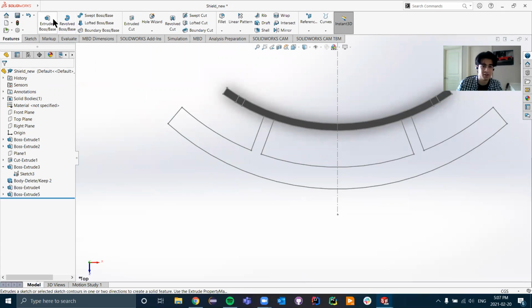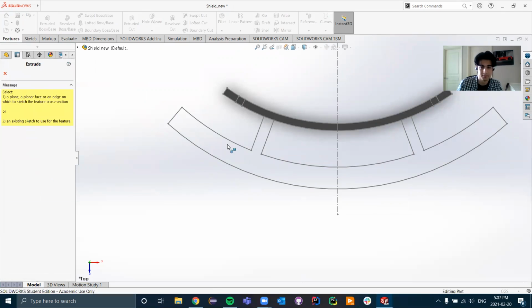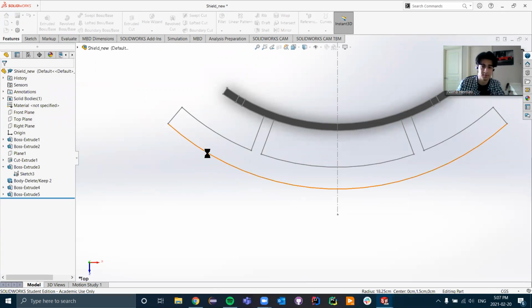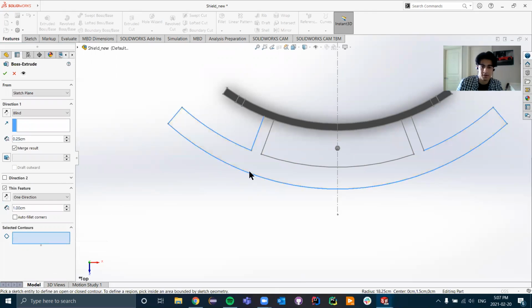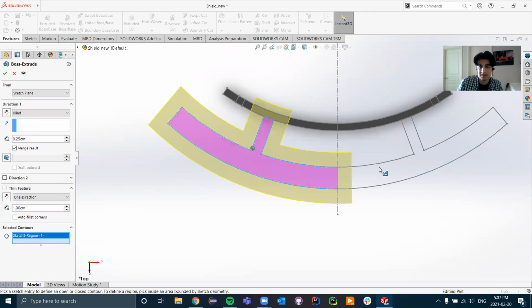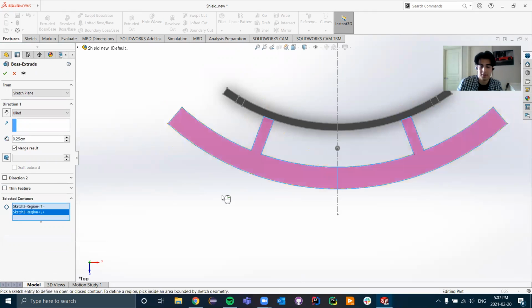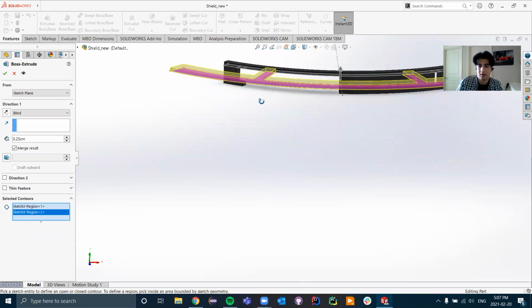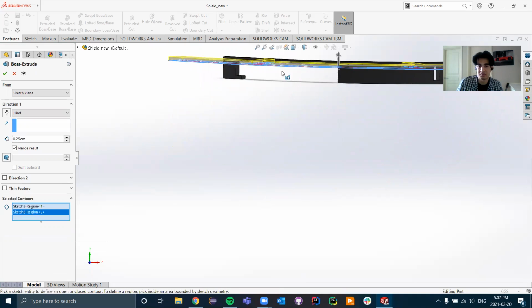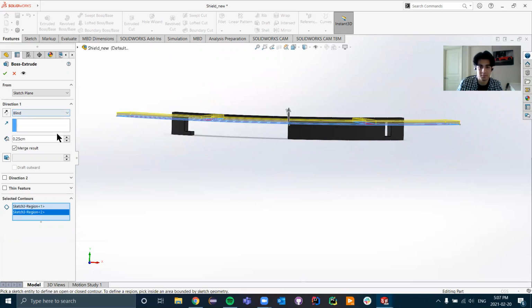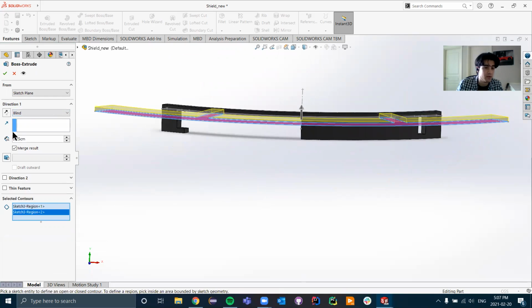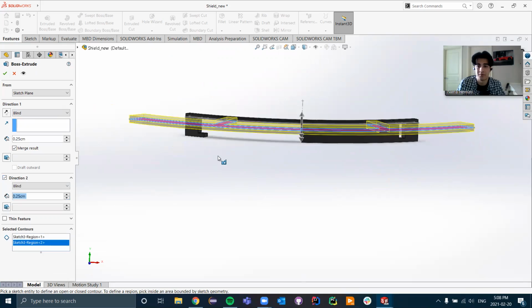Now what I'm going to do is I'm actually going to extrude this as well and click this contour instead. And then clear our selections and essentially click on either side, deselect thin. And now what we can do is we can actually extend this below. So we can do it in both ways. So what I'm going to do is I'm going to actually have this go in two directions. So automatically it's going to match the top length of our extrusion.